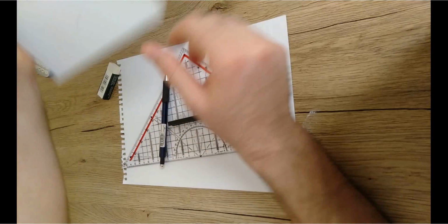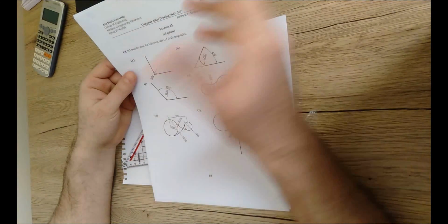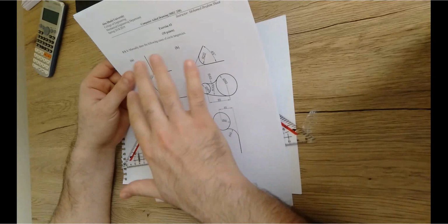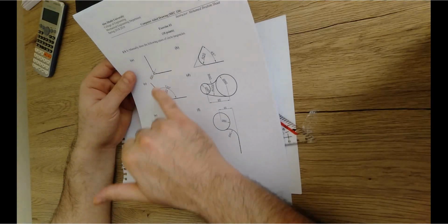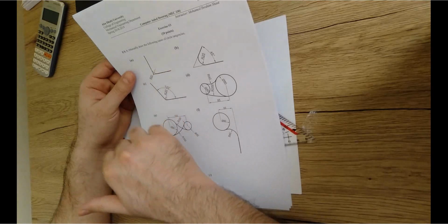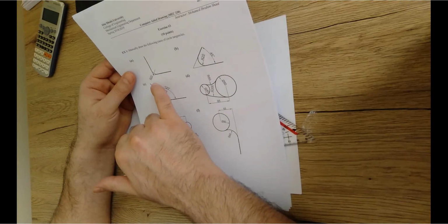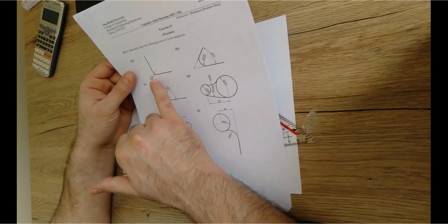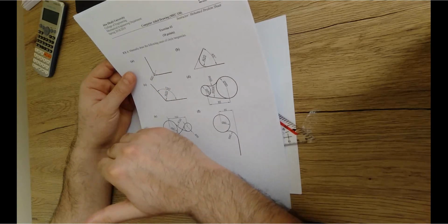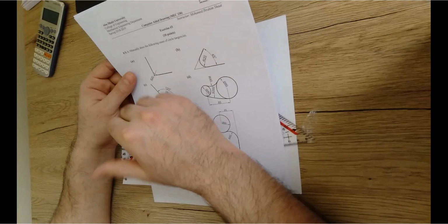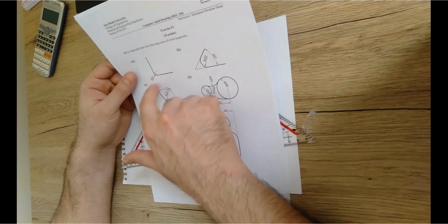Let us start with this very simple example where you have two lines. As given here, the lengths of these two lines are not given, but our main interest is just to draw the curve that is tangent to these two lines following the engineering drawing. As we explained previously, in case you have a curve that is tangent to a line, you have to draw another line that is parallel to the original line, with a normal distance between both of them equal to the radius of the curve.